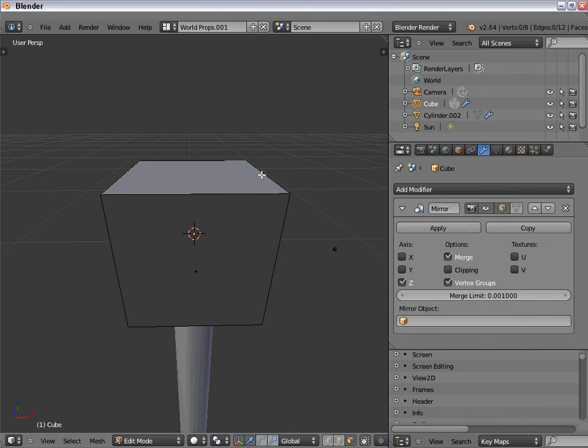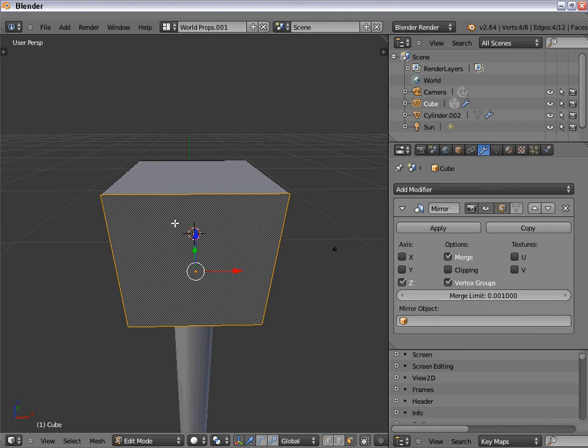Now I'm going to select the object and let's work with the edges. I'll press Ctrl Tab and select Edge Mode, which you can also select using the button down here. In Edge Mode, I'll press the Alt key and select the edge with the right mouse button.